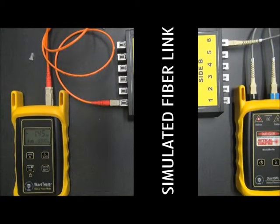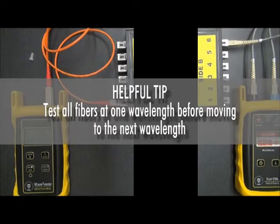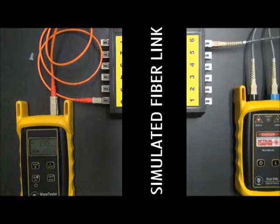Now, this is a helpful tip. It's better when you're using a WaveTester and a dual OWL in particular, it's better to store all the readings at one wavelength first, and then once you have all those readings stored, then switch the wavelength. That way you only have to switch the wavelength once. You only have to switch the patch cable once. It keeps the test results organized, and it's a lot quicker of a test.